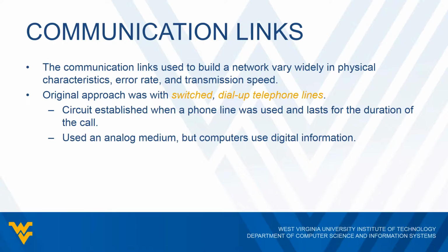This was fine for transmitting human voice because it varies continuously in pitch and volume. But a computer produces digital information, specifically a sequence of zeros and ones. So in order to transmit this through a telephone line, we need to be able to restructure these binary numbers into an analog representation.